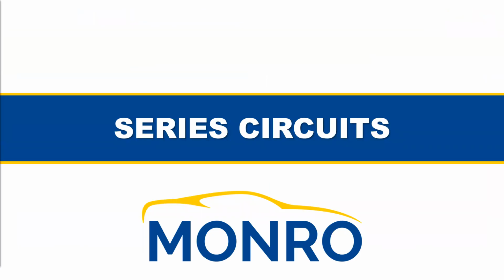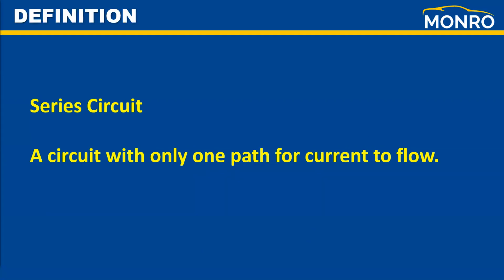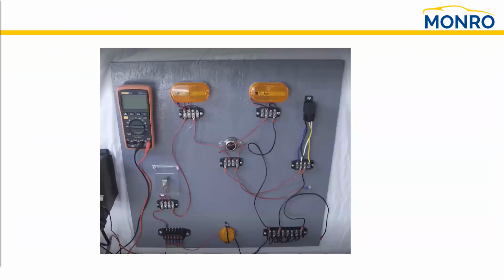So let's talk about series circuits first. First, we need to define what in the world is a series circuit. By definition, a series circuit is a circuit that has only one path for current to flow. Here's what I mean by that. We take a look at this circuit that's wired in series. We start at battery positive power. We run power to the switch. From the switch, we run up to the first load. Then we run power through the first load to the second load, and then we use a single ground back to the battery.